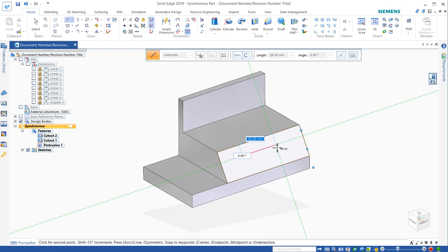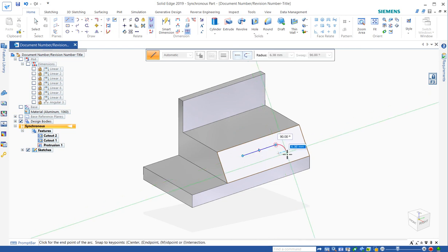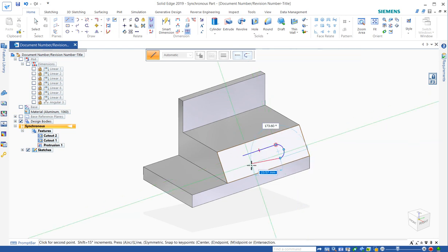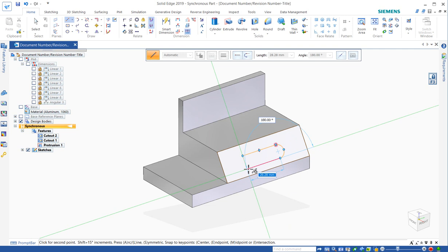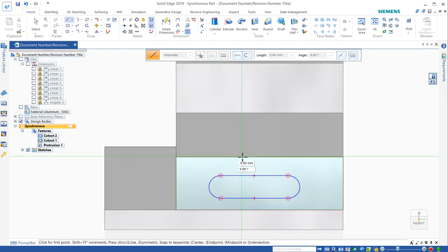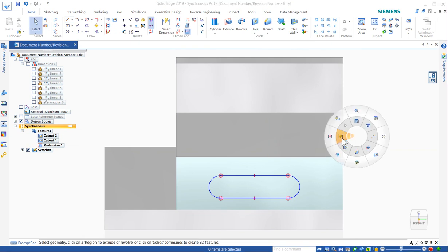So when I click this and lock, now I can go and draw a little shape here, and again this is synchronous mode, but it's just a little shape. To be honest with you, because in synchronous mode it doesn't really establish a plane by moving the model like this automatically, Control H. Sometimes you won't notice that your plane is 90 degrees off.